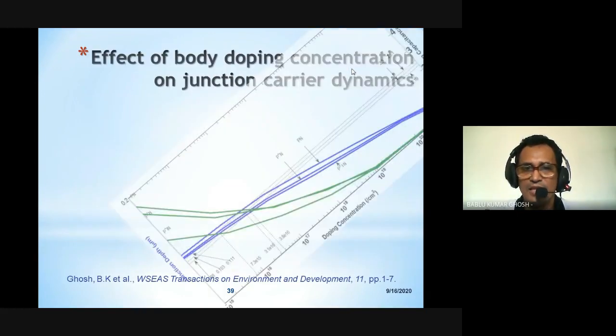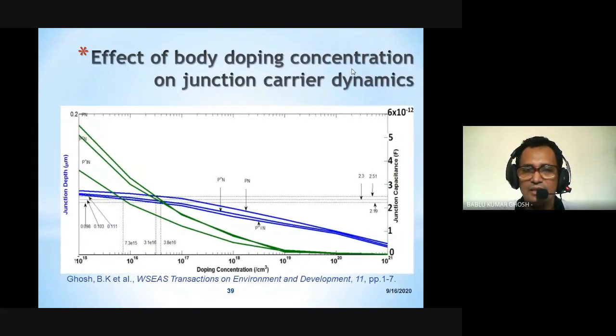At the same time, you can analyze where the junction should be to make an effective solar photovoltaic with the absorption edge. Here you can see that P+IN, P+N and PN had different depths of the PN junction, which also made variation with the different doping concentration. Ultimately, it is very significant background work to develop high efficiency solar photovoltaics.